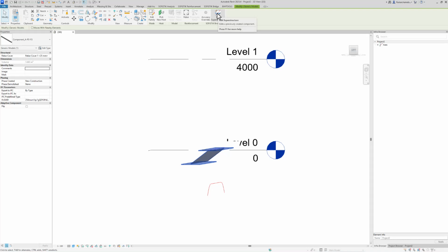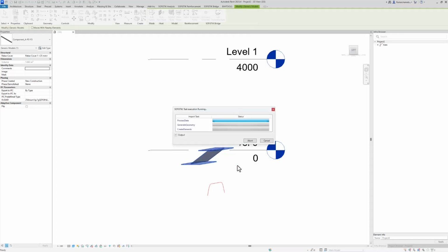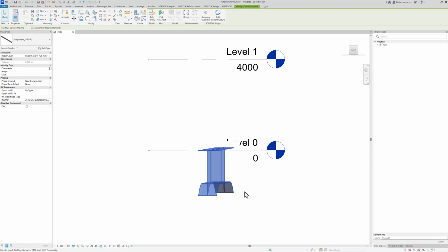So I can go back to edit this superstructure, either select it via the 3-dimensional selection, or in the drop down we can find all the secondary axes that are available based on the main axis. I can select A vertical, and the program will automatically find the secondary axis and assign the shape handle point to it.